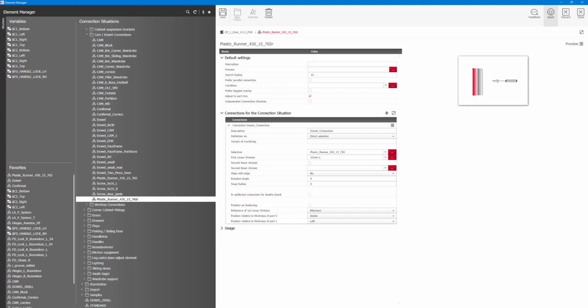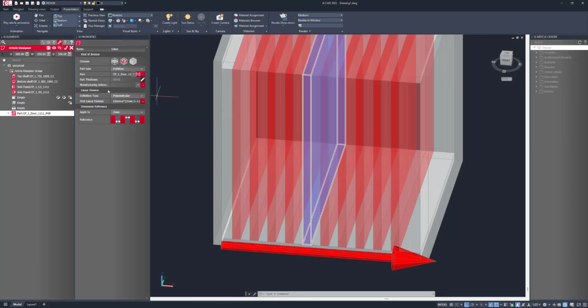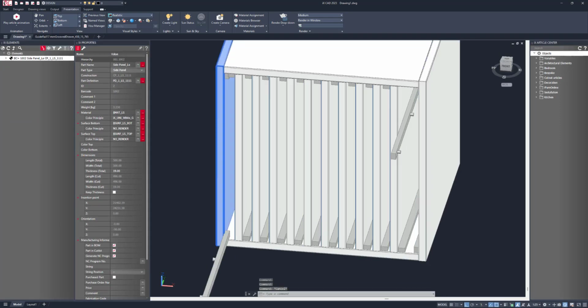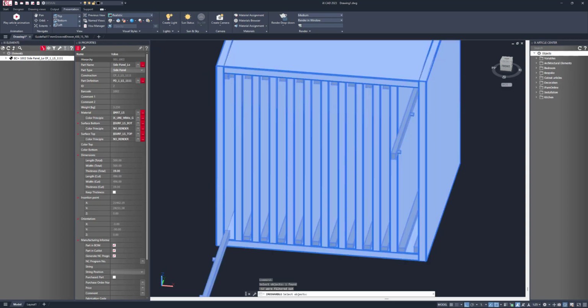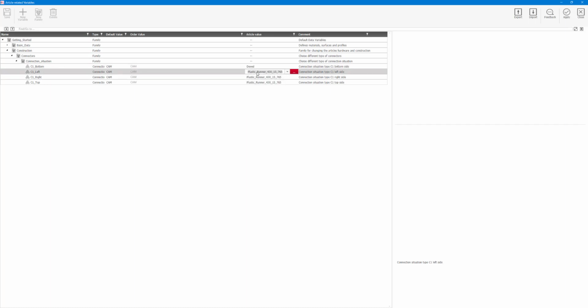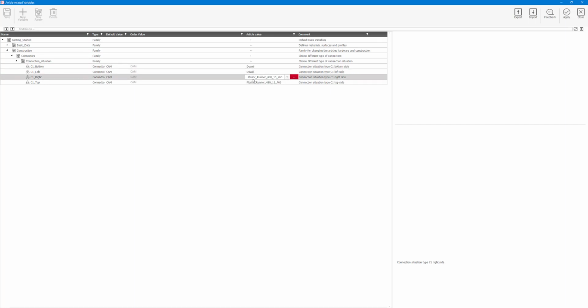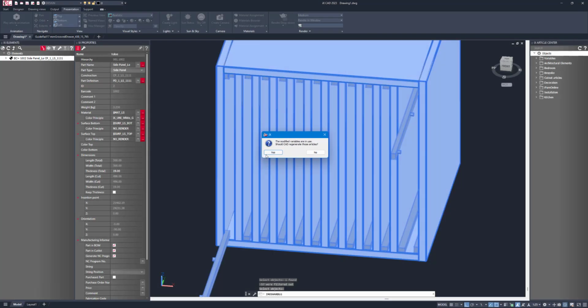Let's save that, apply that. Tick. There we go. If we then go back in article related variables, we just want to quickly change this now to be the original dowel fitting that we were using to knock this cabinet up. And click apply.